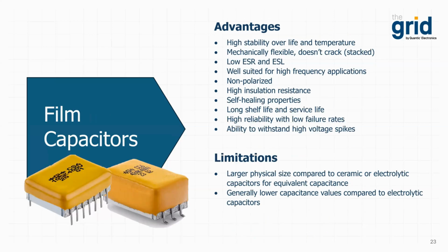Film capacitors are particularly valued in avionics for their reliability, electrical stability, and their ability to withstand harsh environmental conditions, making them suitable for many critical applications in aircraft electrical and electronic systems. They do come in a variety of form factors, including wound and stacked. Now, some advantages include they are highly electrically stable over life and temperature.